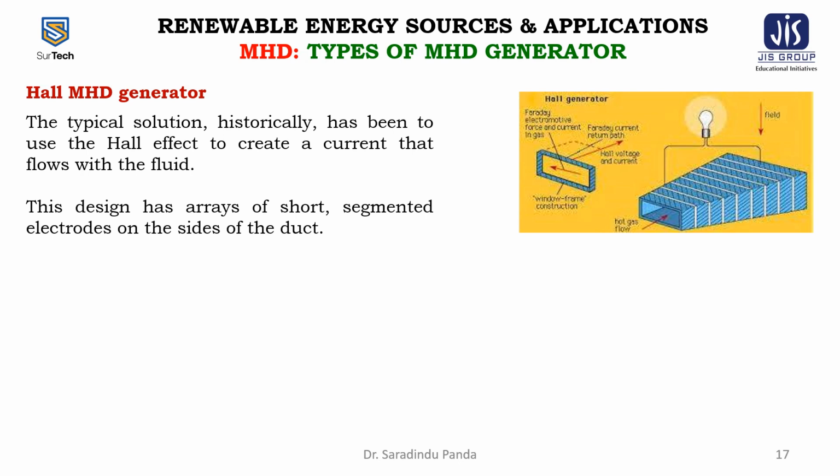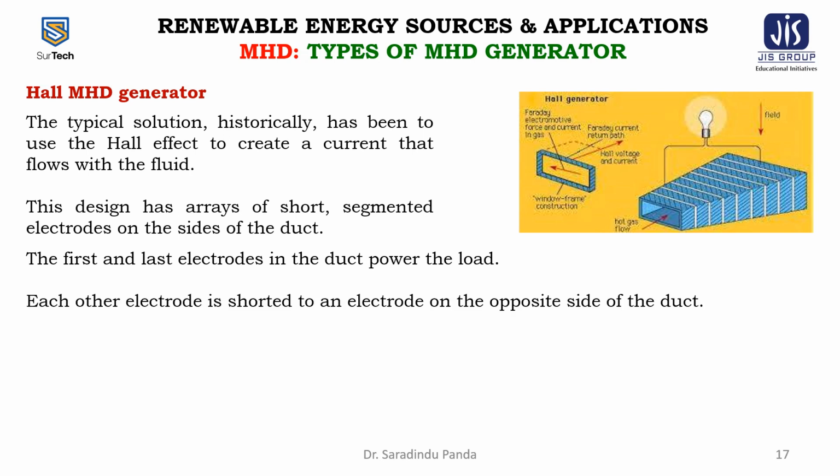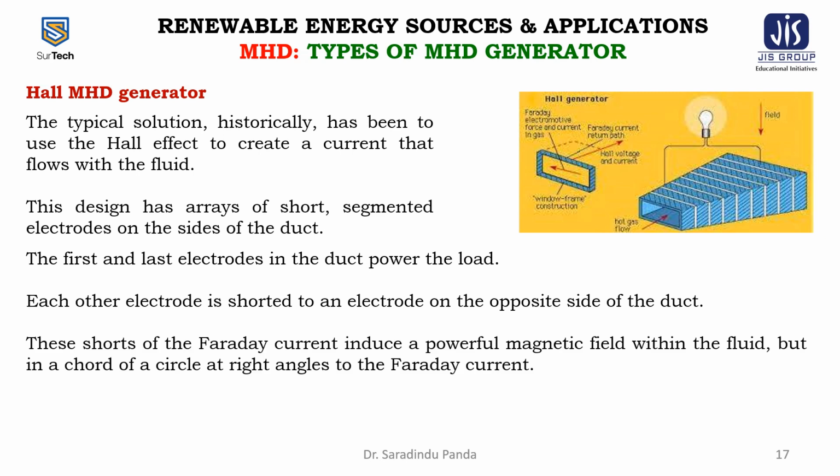This design has arrays of short segmented electrodes on the side of the duct. These are the electrodes. The first and the last electrodes in the duct power the load. Each other electrode is shorted to an electrode on the opposite side of the duct.